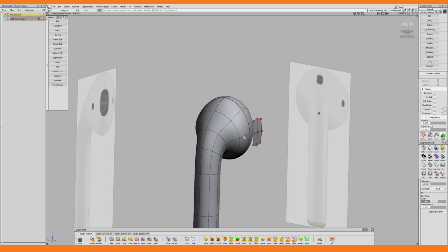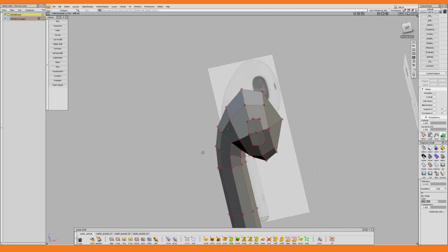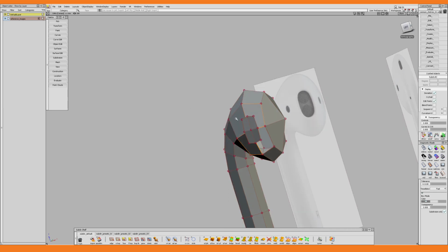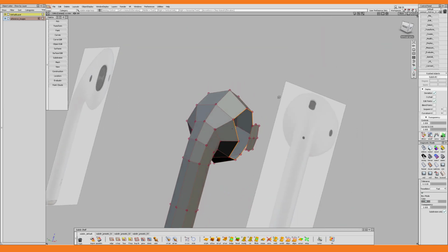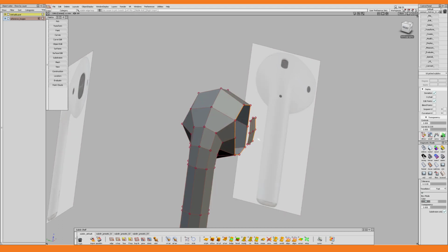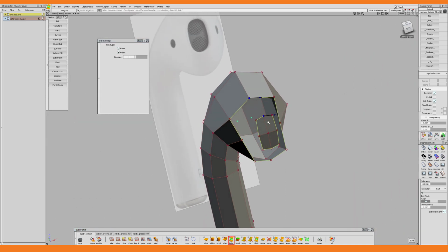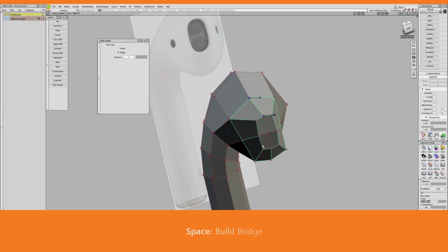Then it's just a matter of connecting these two objects. But before I can do that, I need to create an opening, which is why I am deleting these 4 faces. I also use the scale tool to planarize all these edges, since I think that will yield a better end result. With the border edge loops on both sides selected, I can then once again make use of the bridge tool. And notice how this time the arrows are aligned properly, while I can simply press spacebar on my keyboard